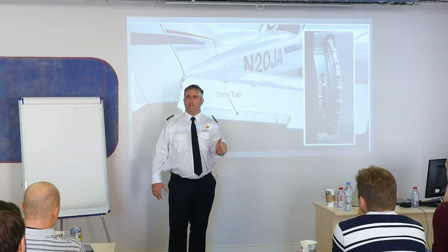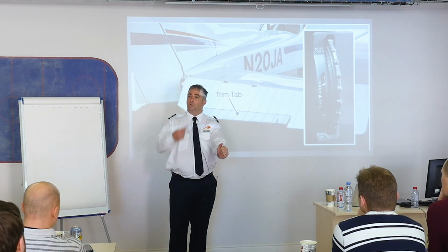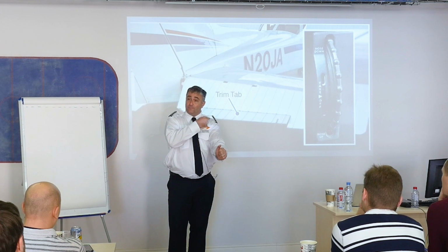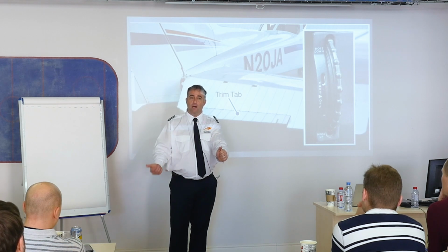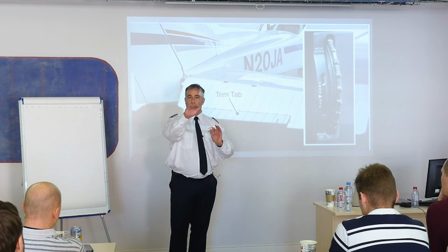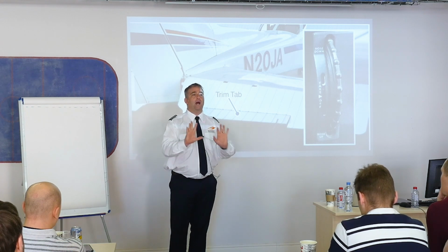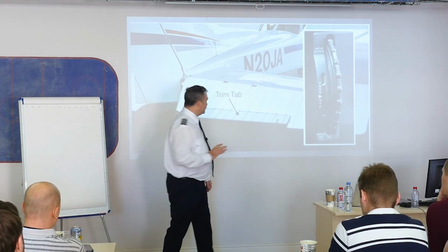That's going to be a very aggravating flight. I'm flying 3 hours pushing on this control. This is terrible. That's what your trim tab is designed to do, to relieve that control force. So now I don't have to use any, perfect. The airplane's exactly where I want it to be, and I'm not pushing or pulling on the controls. That's how you use the trim tab.